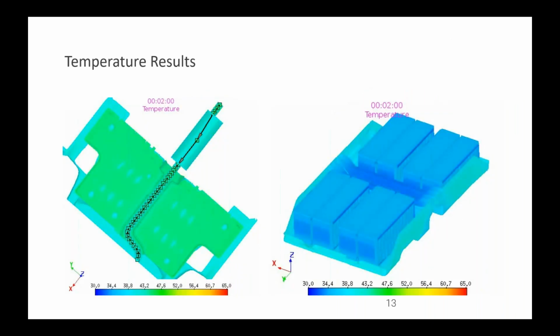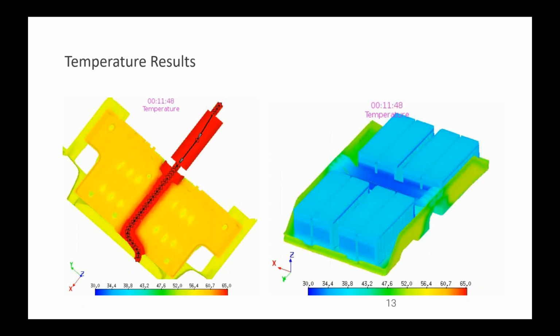So these are some of the results from the software. For the first 10 minutes, the batteries are driving the vehicle, and so they're heating up from discharge. And then after 10 minutes, the vehicle turns on, the exhaust pipe heats up, and the batteries go into a charge mode, which is actually a lower current in this case. And in that case, the batteries are still heating somewhat from discharge, but the main consideration in that case is then shielding the batteries from this hot exhaust pipe.